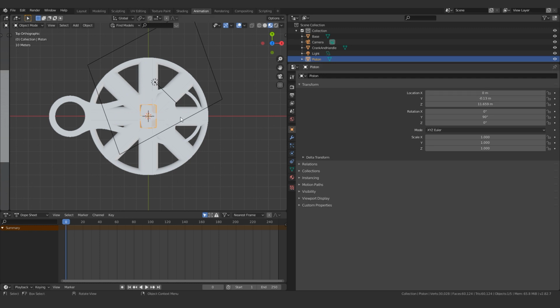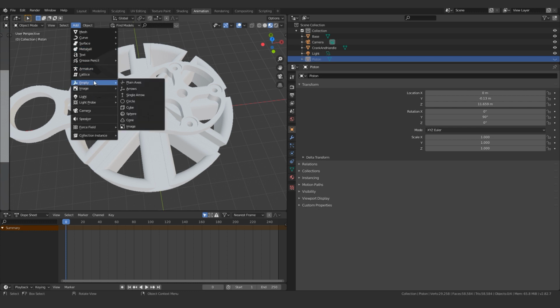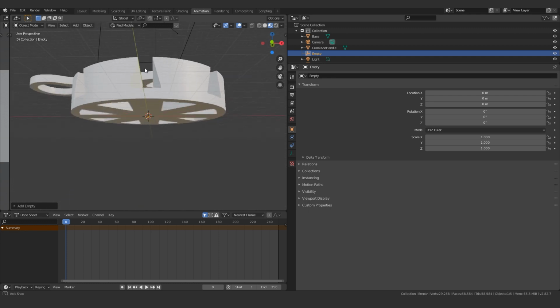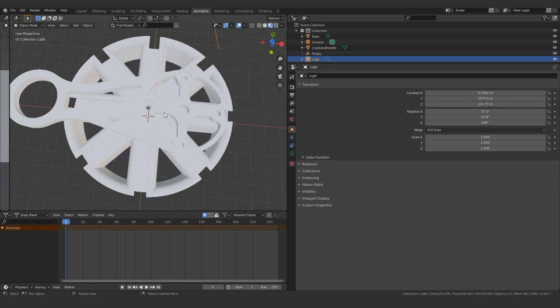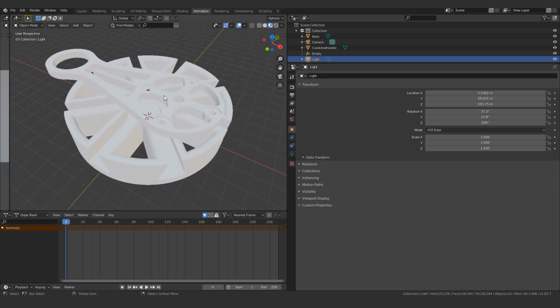Once I'm done that, I'm going to place an empty sphere where I'd like this piston to rotate around. Well, technically it's not rotating, but it is following the position. This will act as our pin. I'm going to position the sphere where I'd like. Once I have the rotation point set up, I'm going to use the Dynamic Parent tool to parent the piston